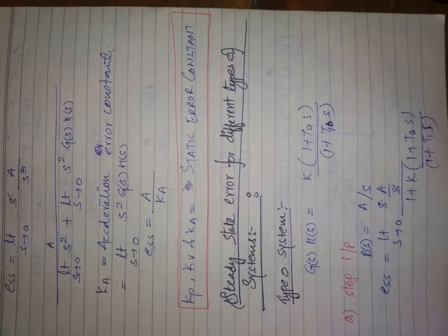If you are asked to find what is error due to changes in input, you can't put D=0 in the diagram. ये ऐसा नहीं कर सकते आप। If you are asked to find what is error due to disturbances, you cannot put R=0 in the diagram. This you can do only for transfer function. If you are asked to find transfer function C by D, then you can put R=0. If you are asked to find transfer function C by R, then you can put D=0. ये सिर्फ ट्रांसफर फंक्शन के लिए ही है, क्योंकि ट्रांसफर फंक्शन इज फॉर आउटपुट एंड इनपुट बट नॉट फॉर एरर, क्योंकि ये एरर जो है दिस इज नाइदर एन इनपुट नॉर आउटपुट, इट इज अ इंटरमीडिएट क्वांटिटी.